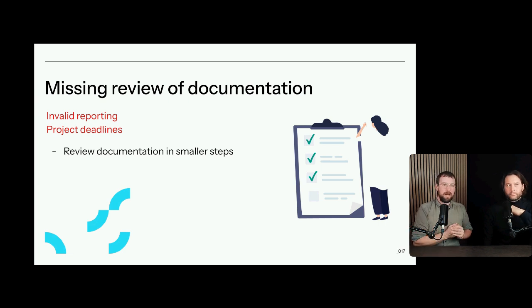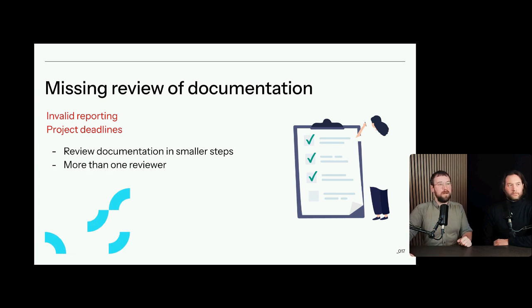And there you find out that there's a mistake. There you find out there's some missing documentation for where a certain logger was placed, or whether it was actually confirmed that it was placed in that location. And then what do you do? Then it's a lot of both time and resources to trace back and assess whether this is still relevant, is it still valid documentation. So reviewing it in smaller steps along the way is a real time saver. Another thing is really also to have more than one reviewer.